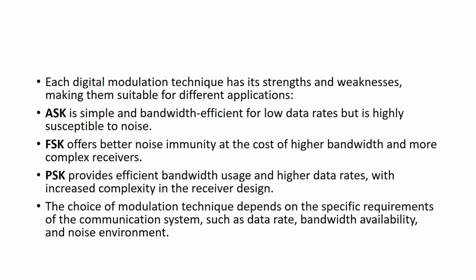FSK offers better noise immunity at the cost of higher bandwidth and a more complex receiver. PSK provides efficient bandwidth usage and higher data rate with increased complexity in receiver design.